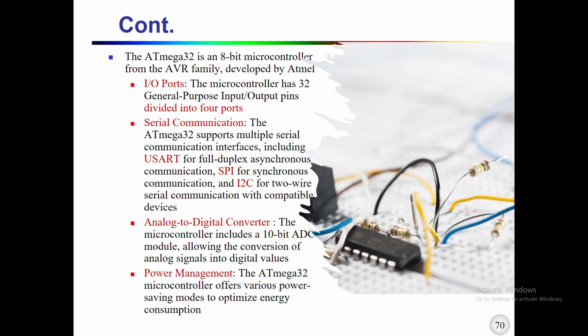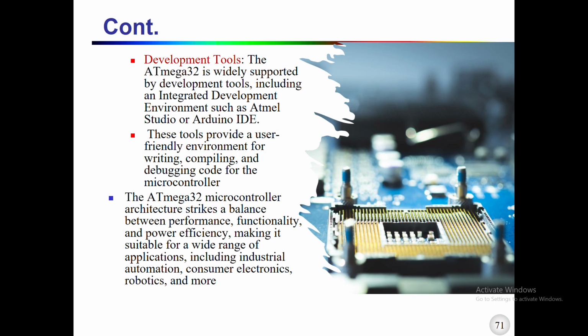The ATmega32 is an 8-bit microcontroller from the AVR family, mostly developed by Atmel. The input output ports of the microcontroller have 32 general purpose input output pins, which are divided into 4 ports, plus the serial communication UART, analog to digital converter, and power management pins, which we have already discussed in our previous sessions.